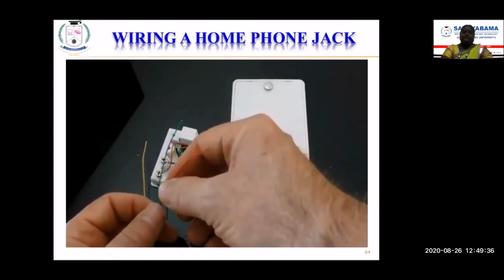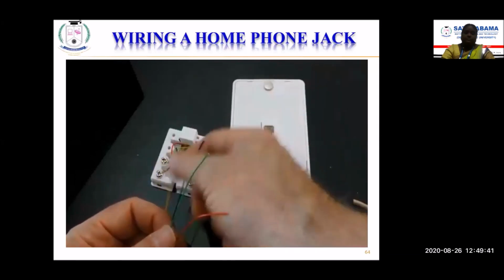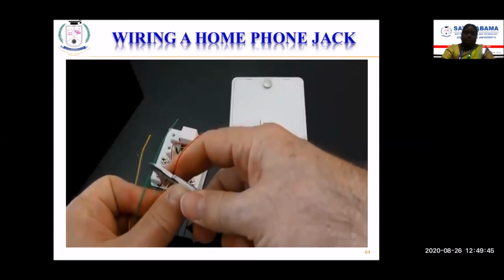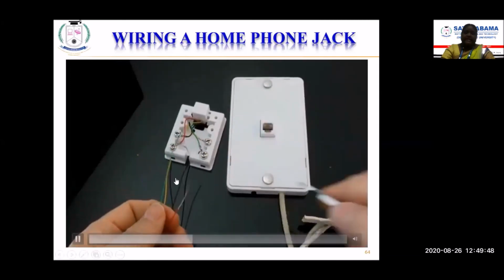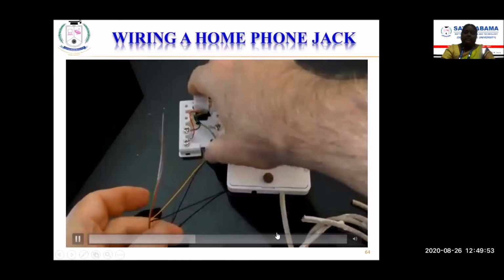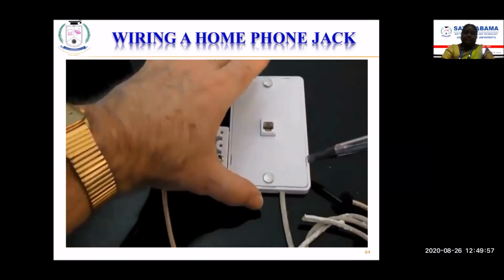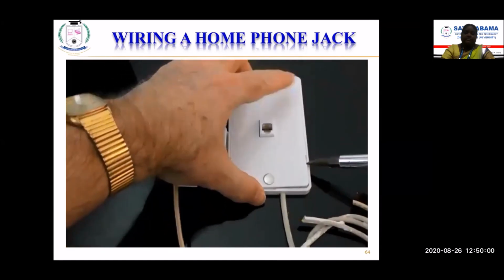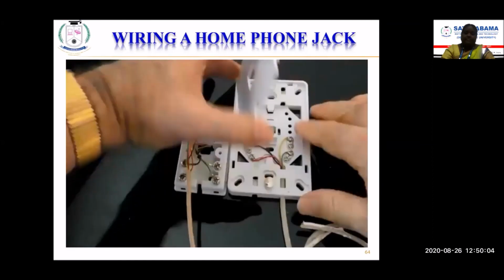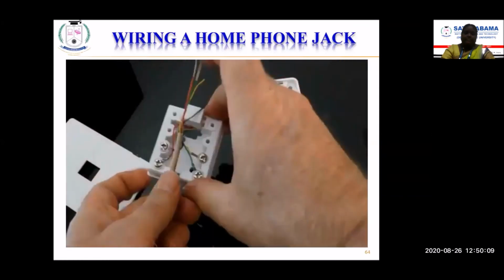So what we have to do now is, within these conductors, they've got a little bit of plastic sheath on them, so we want to peel that back. I'm going to peel off about 2 or so inches of the plastic sheath to reveal the copper. Then on my screw post, and this is true for this type or the flush mount, you'll see it on the back, but on these, there's a little spot where you can pry off the cover, and you'll see inside, it's got the same screw post inside. All you're doing is just matching the colors.